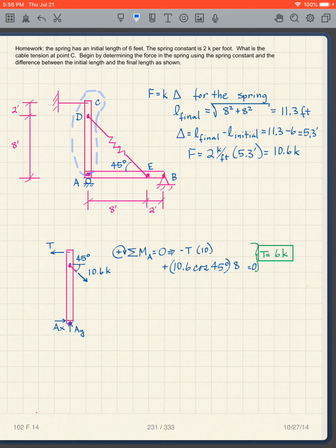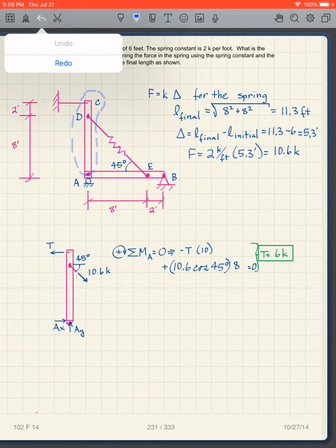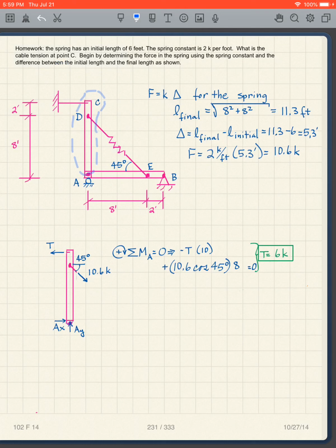Okay, first of all, the only two-force member here is the spring. In other words, this is not a two-force member because it's attached at the ends here, and I have another attachment in the middle. And similarly, I have the two ends attached there with another attachment in the middle. So the only two-force member is this one. It's a spring. We treat it like a truss member, as I said.